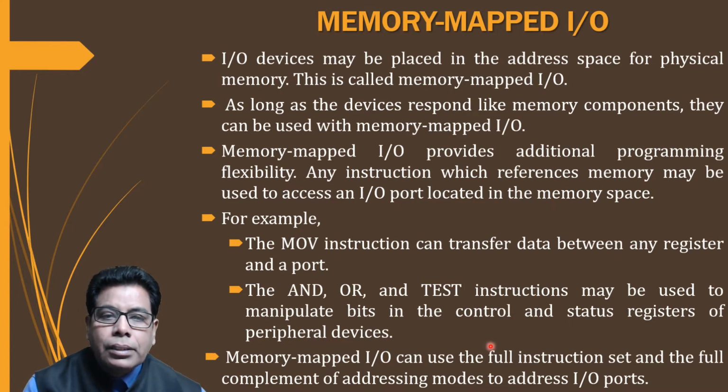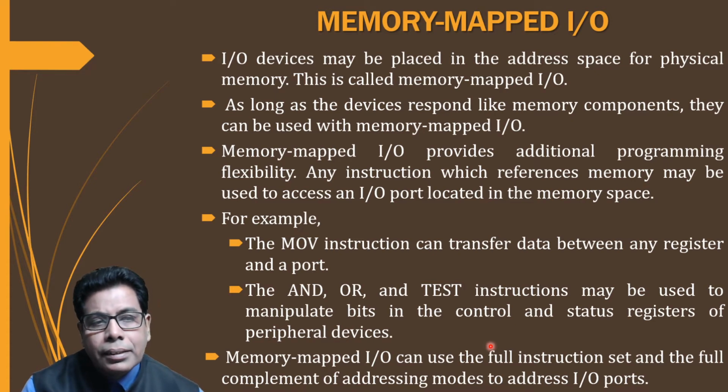When we are using memory mapped I/O, we have additional programming flexibility. The same instructions which reference memory can be used for accessing the I/O port located in the memory space, because the address for that will be the same as for memory, and so we can treat the I/O as memory and the same instructions can be used for programming.